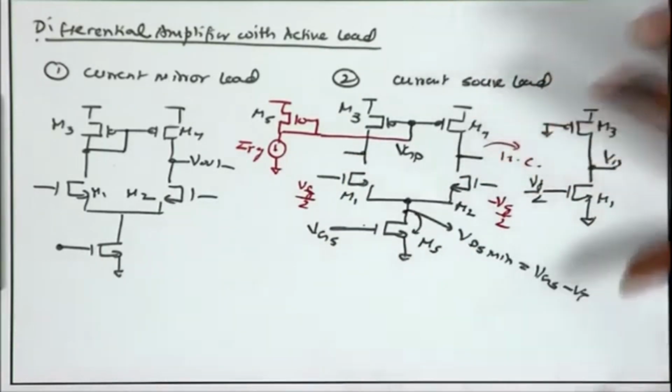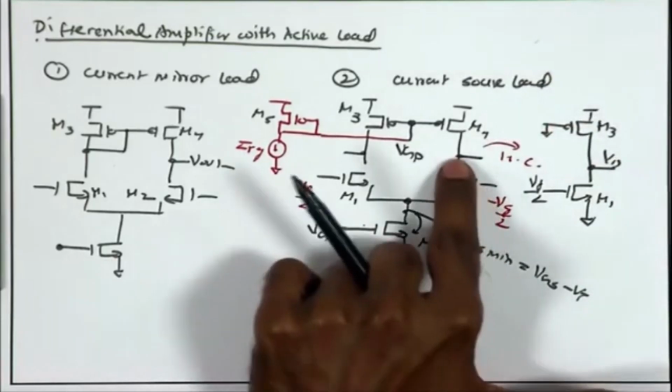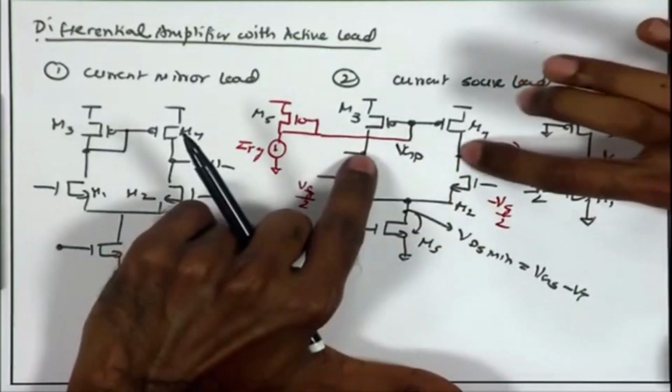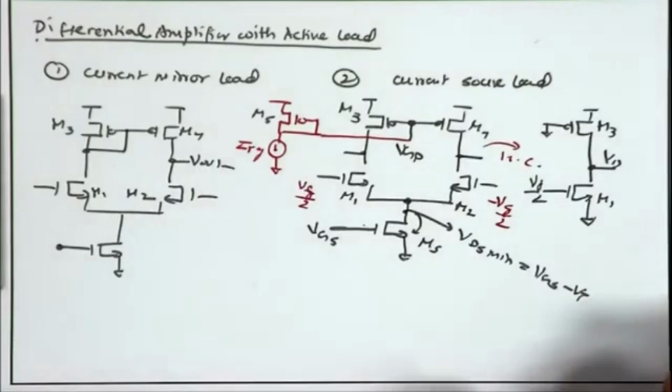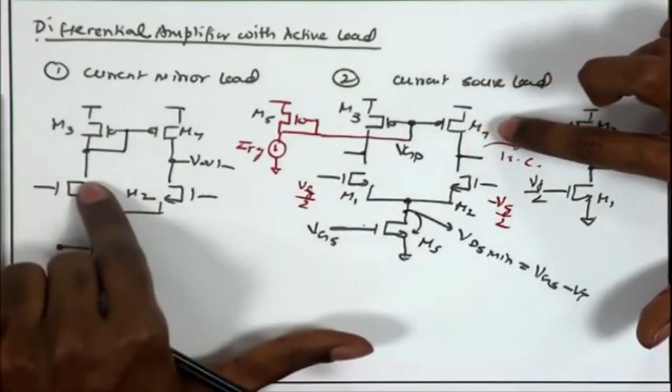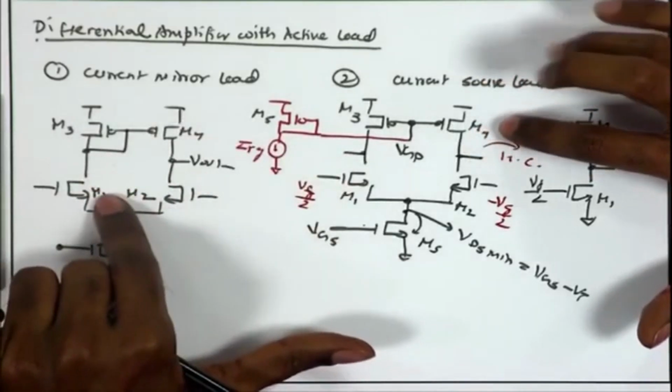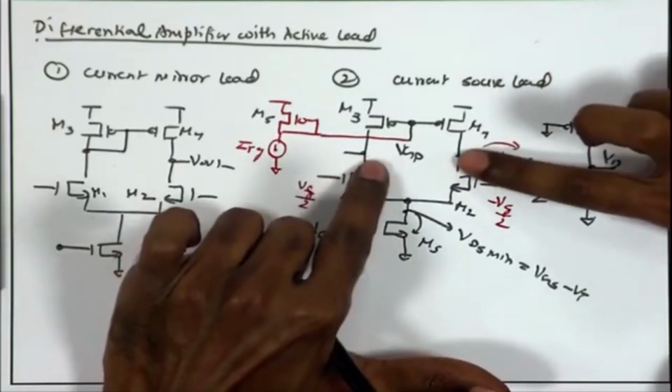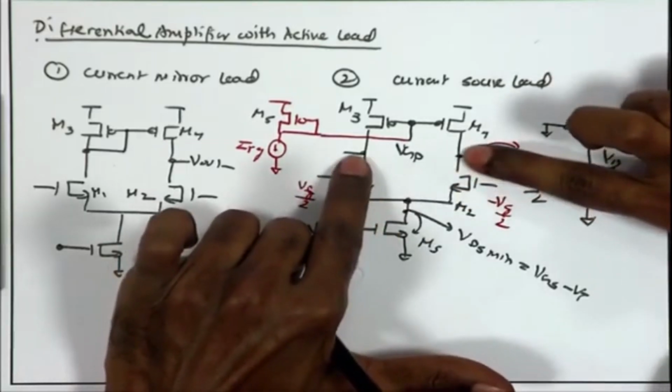But in differential circuits, we do have some mechanisms through which we can try to stabilize the Vd. So, we will see how, with the help of the second amplifier over here, which is the amplifier with current mirror load, we can obtain a desired DC point at the output of this